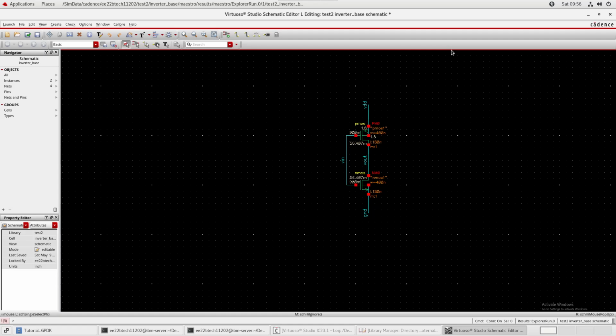Like an op amp internally may have a lot of nodes, a lot of devices, but what you really care about is just your input, maybe your differential input, maybe your differential output, the supply, ground, maybe some bias current. That is all that you care about. Internally, there may be 100 nodes present inside. You don't care about them. You just care about these input output nodes, the power nodes.